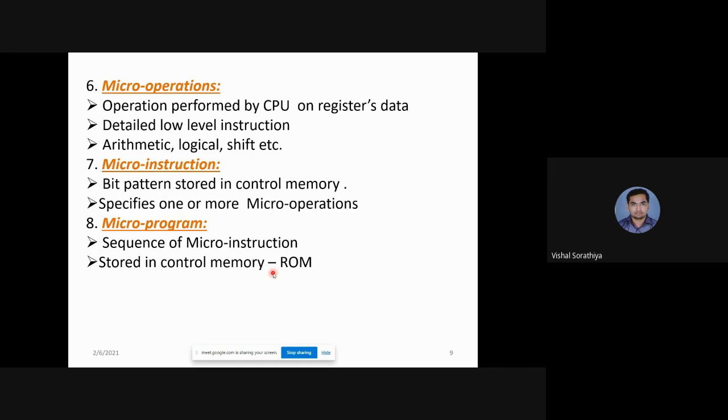That common micro operation will be like, when I say add, it means there is a specific thing: you need to turn on your accumulator, you need to turn on your bus, you need to turn on this particular thing. Whenever I'm doing the addition, the accumulator is always going to be on. So whatever the micro operation is, it is going to be common every time.